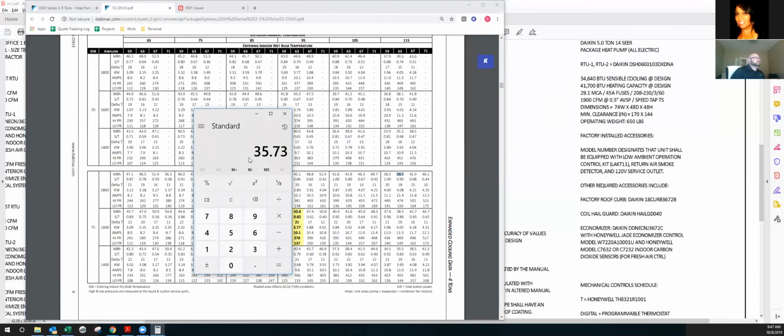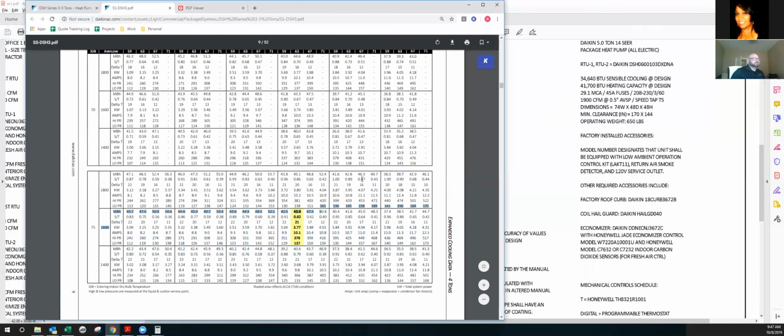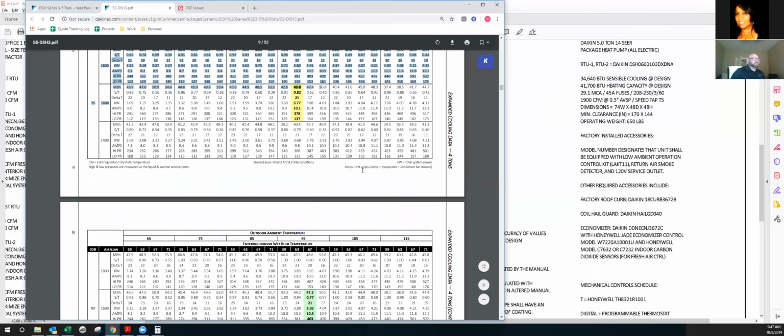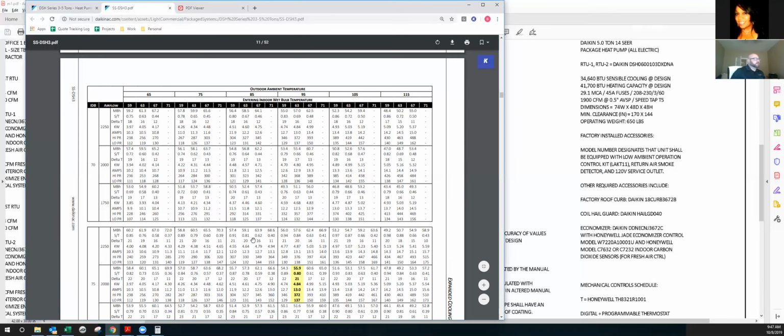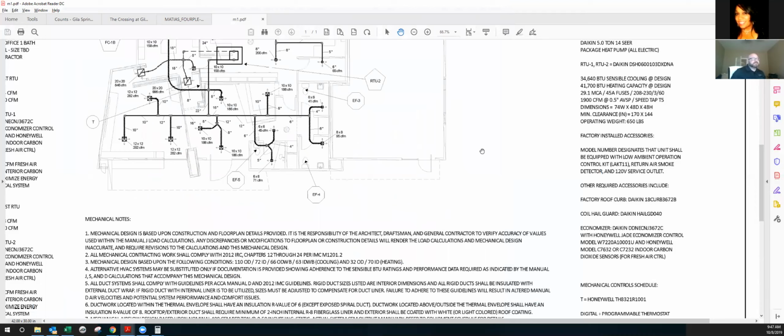Okay, that's helpful. So that's where we can be of value and bring a service to our customer. I go back to them and provide them this expanded cooling data and an interpretation of it, saying, hey, you selected this, but you may be setting yourself up for short cycling at this 110. And so that's kind of how the math all translates. Okay, so that's expanded cooling data.